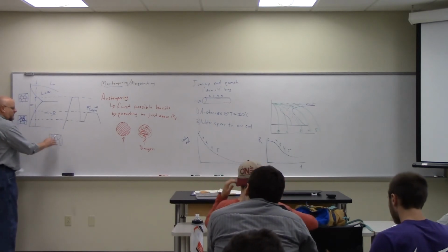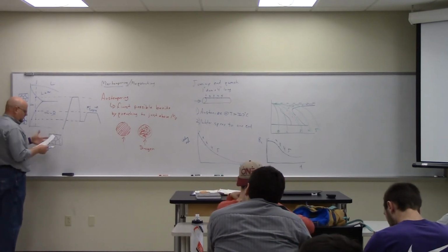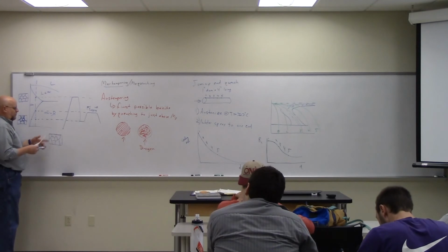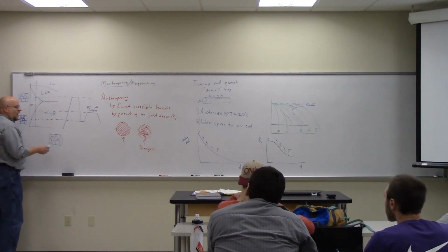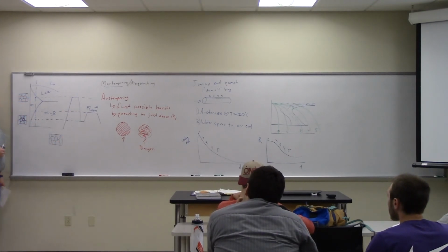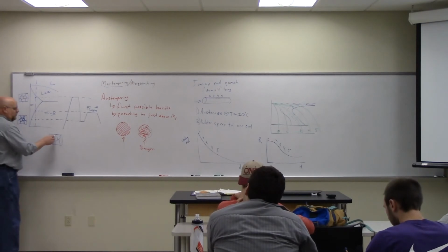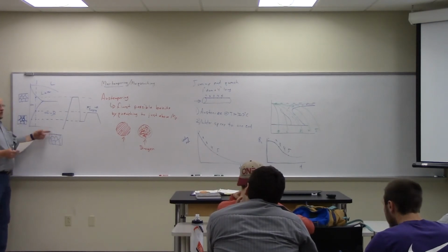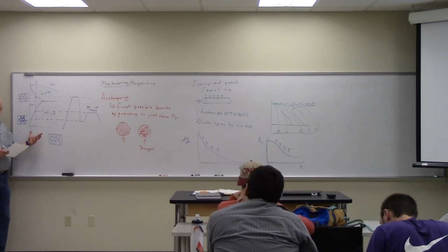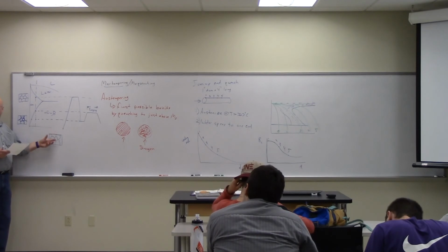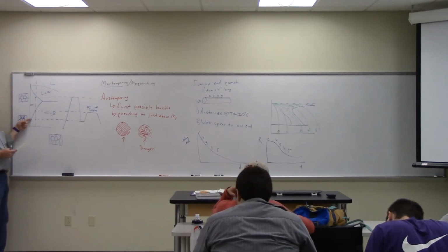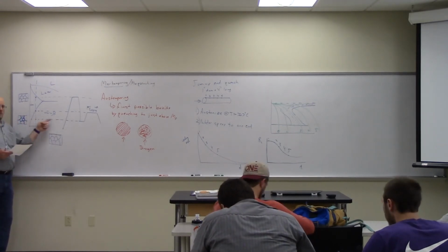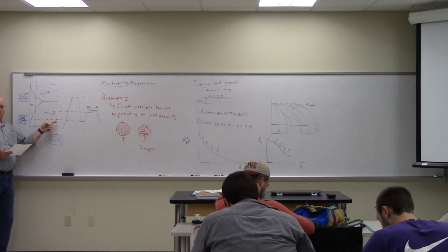So they end up forming these things all over and getting this sort of speckledy look. Okay? And then I quench that down. What's going to happen is those locations are going to be locked in, and then beta will start forming at those sites. So I'll basically have formed beta at all those sites in the proper proportion in order to be at equilibrium. Does that make sense?